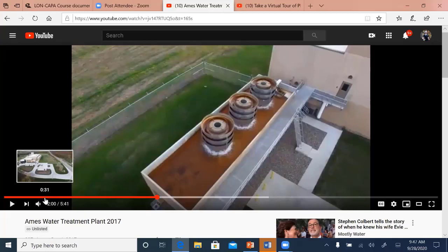Also in many cases, for instance the East Lansing system, the MSU system, iron and manganese levels in the groundwater are quite high. And often we want to remove the iron and manganese in order to produce higher quality water. Now we can use an approach like MSU is using with an ion exchange system. But the system that they've chosen at MSU doesn't remove hardness. It removes iron and manganese, but it's not going to remove hardness.